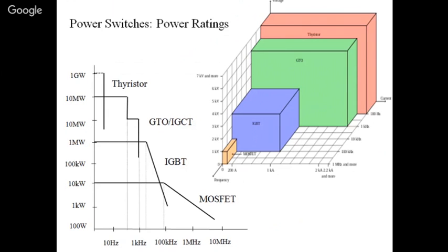Then why do we go for all these switches? Fast switching might be. That also you can do, not very high switching, but switching is possible there also. In the machines lab and all, we used to have double pole, double throw switches and all automatic switchings. All these things are there. But the main advantage of these power electronic switches, they are static switches, we say. They don't produce any arc or any flashover. Usually in these switches, there will be a small arc formed and there is some loss there.